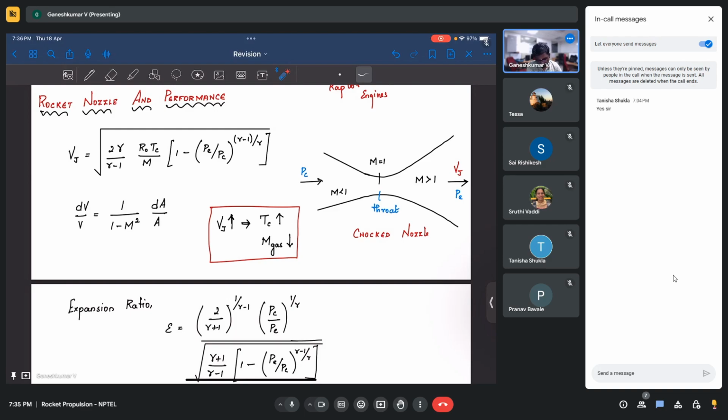Okay, and in the nozzle we applied compressible flow theory. Basically, we apply isentropic flow; those are a few assumptions you should remember. Whatever we did in this course, we assume that it's an isentropic flow, which you can assume to a certain extent. If you use this isentropic flow theory and you're able to predict things, that will be closer to, let's say, 90-95% of the reality.